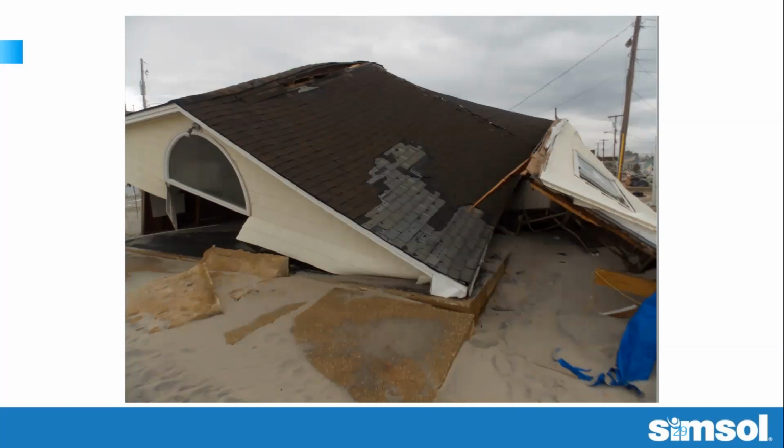In this case, these unreinforced slabs of concrete that were about 50 yards in front of this building were picked up by the surge, battered into the building, causing it to collapse, and then subsequent runoff peeled the shingles off. But the actual damage on the top of the ridge is basically the result of the roof falling. Yes. And then that pressure pushed up. Right. And then that's the resultant damage.